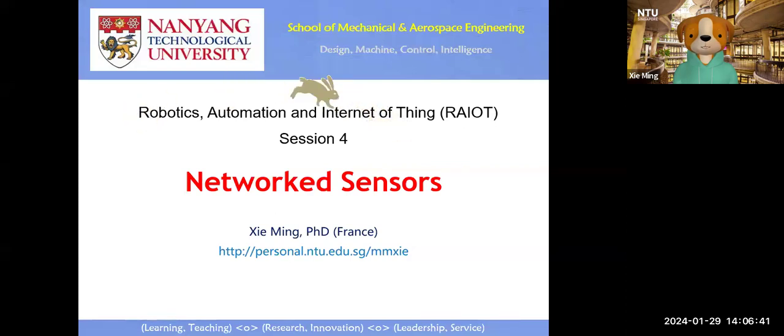But if you switch to asynchronous serial communication, then you can easily build up a three-dimensional network, because for each node of ARM Cortex M4, for example, you have the support of a port for the asynchronous serial communication. Then in this way, you can construct three-dimensional IoT, right?